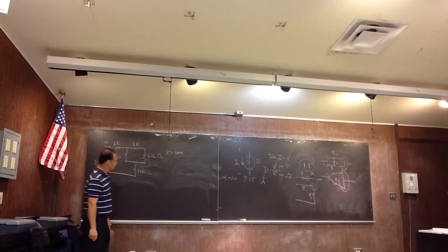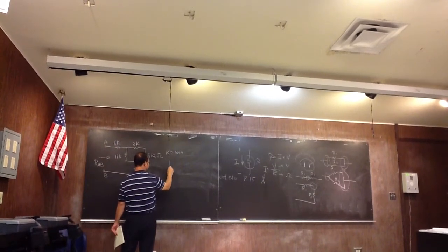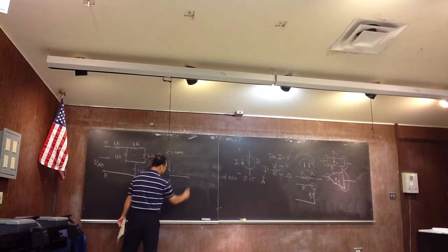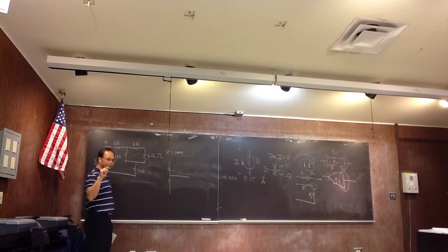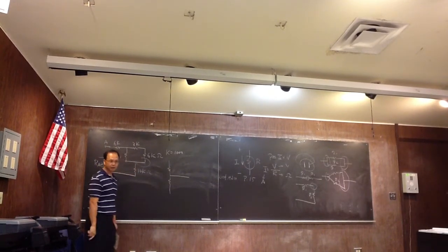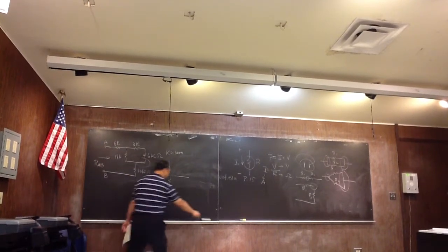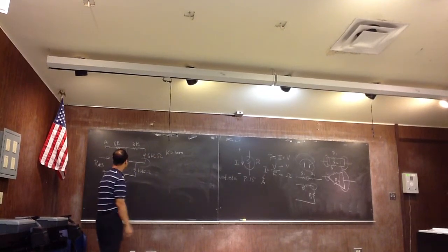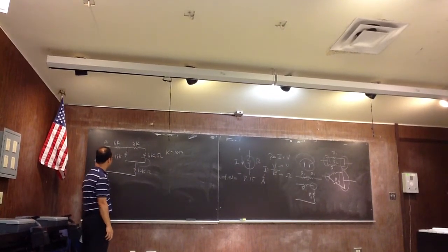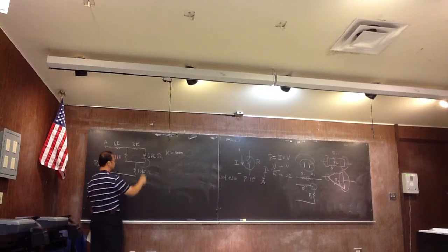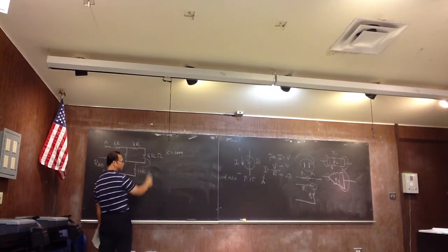I told you last time that would be in series, but if there's another connection right here, then you are not allowed to use the series formula for these two resistors. So the first thing to do is this combination. These two are in series, correct? Because there's nothing connected to the middle.